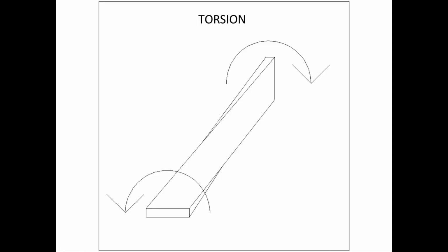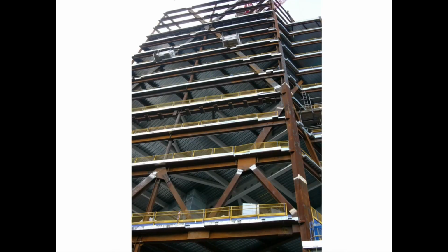There is another way in which structures and buildings can deform, and that is an expression known as torsion. You can see from this diagram exactly how torsion is occurring. In other words, you're getting opposite twists on a structure. It can happen for all sorts of reasons. It can be the design of the dead load of the structure puts these kinds of forces onto the structure. It could be external loads, could be either. So we have to resist structural elements deforming in torsion.